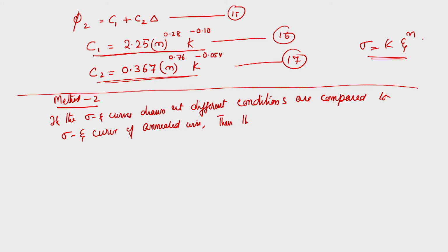The drawn wire will always have a higher stress for a particular strain, compared to your homogeneously deformed tensile pulled sample. Okay. So, this difference is due to the redundant deformation, and the strain in simple tension which corresponds to the yield stress of the drawn wire is thus an equivalent strain epsilon star, which we have discussed.